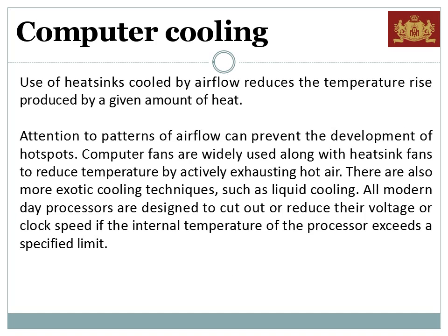Use of heatsinks cooled by airflow reduces the temperature rise produced by a given amount of heat. Attention to patterns of airflow can prevent the development of hot spots. Computer fans are widely used along with heatsink fans to reduce temperature by actively exhausting hot air. There are also more exotic cooling techniques, such as liquid cooling. All modern-day processors are designed to cut out or reduce their voltage or clock speed if the internal temperature of the processor exceeds a specified limit.